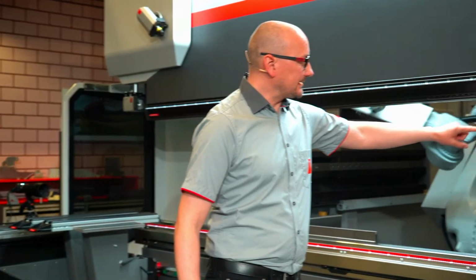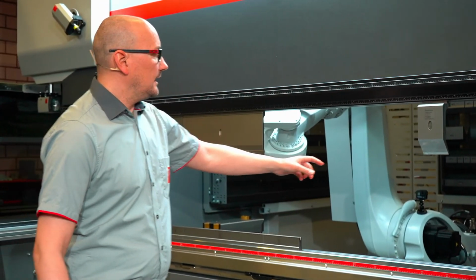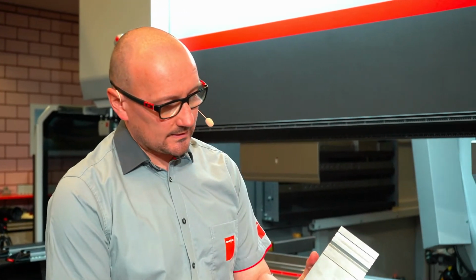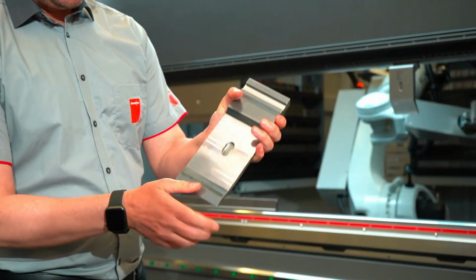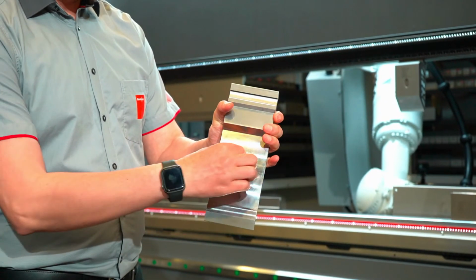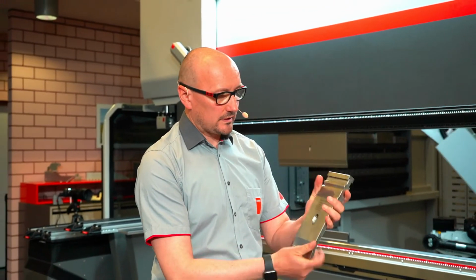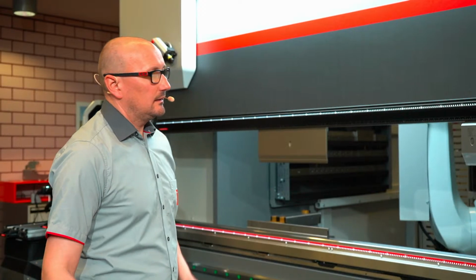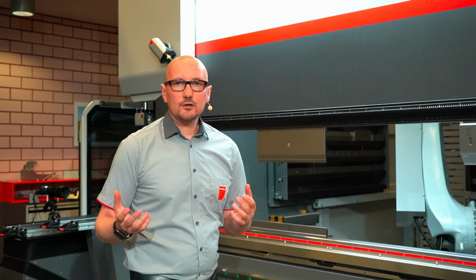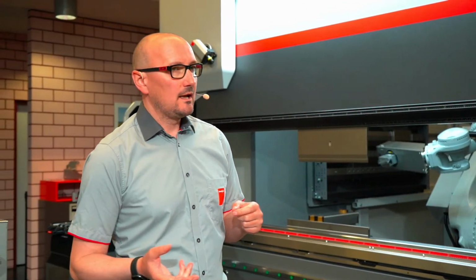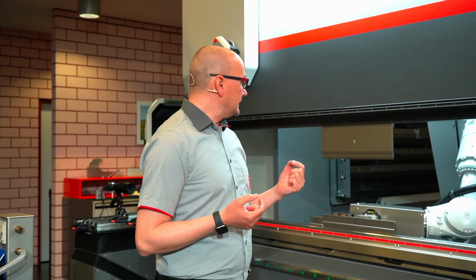What's also possible, you see it on this tool, you can use gooseneck tools like this one. And if you ask me, can I rotate the tool? Of course, you will see it later on, but I can show it this time on this tool. We have these inserts here and also on the back so that we can hold the parts from here and put the part or the tool in the right way on the machine, and we can also rotate this. This is the reason why we also have these little holes in the front, so that we can also rotate the tools. For the rotating function, you don't need the tools double in the stock. We have just one of the tool, and if you like to rotate, then the robot will do it automatically.